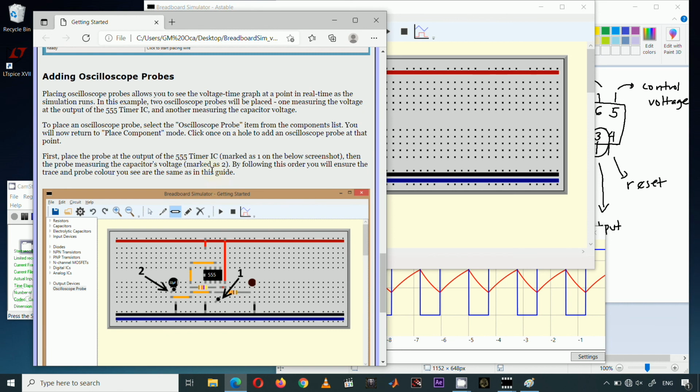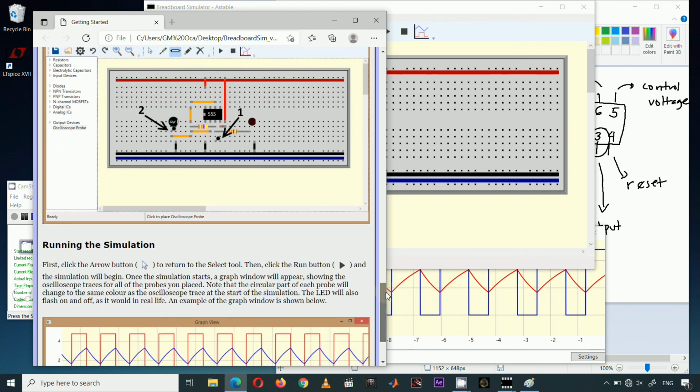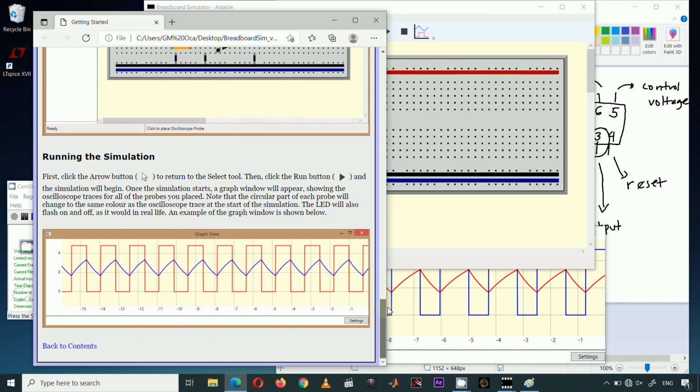Breadboard Simulator doesn't have multimeters because oscilloscopes can act as voltmeter. It just displays the voltage as a single DC signal if you try to use this as multimeter. And when you want current, then you can just use Ohm's law from that voltage DC signal, or use the interact button and hover it to a specific wire or electronic component to show the value of the voltage or current detected on that component. This getting started guide also explains how to run the simulation.